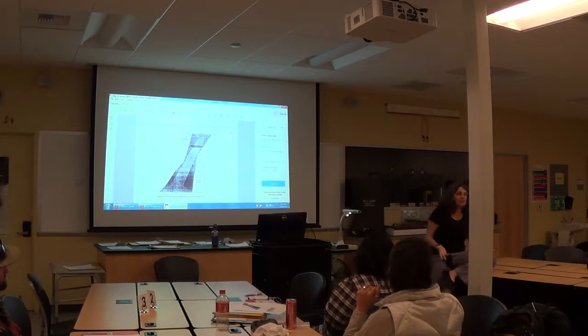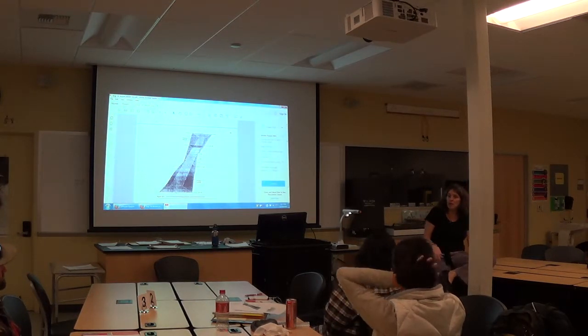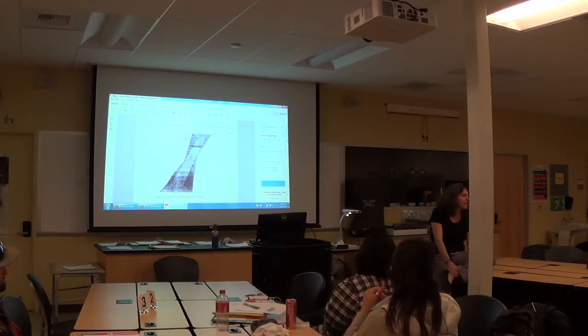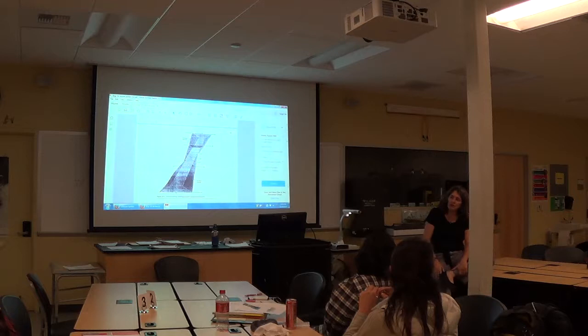But you can't just take dirt from any place because it might have a lot of organic material in it, right? What's the problem with organic material? It decomposes and then you have voids, right? And then you have to compact it or it settles. Peat is an organic material, that's not good. So you always have to have the geotechnical engineer test the soil to see if it's okay for fill material. So in the case of removing it and putting it, I think you still have to go through that process. Yeah. It could be organic material that you're picking up, or if it's too clay, you might not get the right compaction.